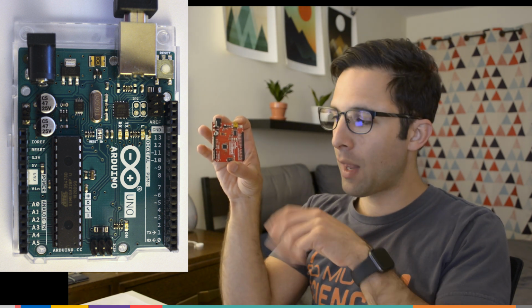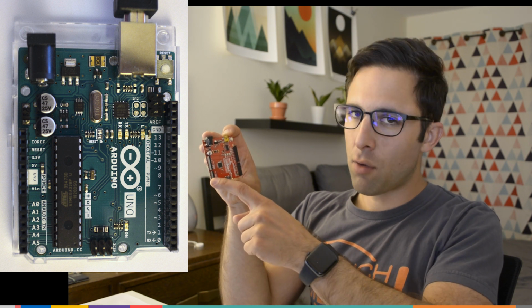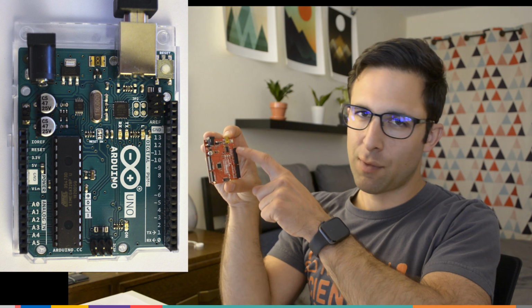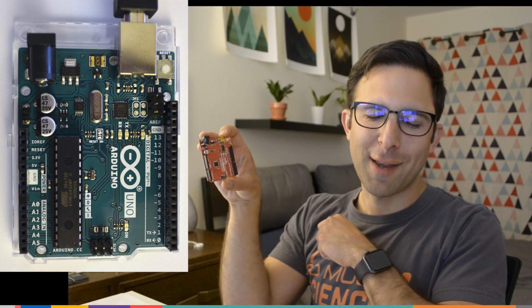I'd recommend using pins 2 through 13. Those are all going to work as we described, just like you'd expect. There's a way to use these analog pins as well, but you don't want to use pin 0 or 1, and then the pins up here can get kind of complicated. Read up on it if you're really interested. That's going to be a more intermediate topic.